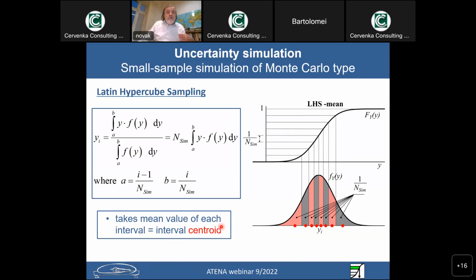Selection of realization from the distribution function is done according to this formula, which is actually the centroid of the layers. Because we produce random variables from the centroid, the mean value consists of centroids, and it is reproduced absolutely precisely. So this is the most efficient technique of stratified sampling available, which was invented by Huntington and Vorechovsky. And we need that because very often we can allow only tens or hundreds of simulations, not more, which is quite a small number in reliability engineering, right?